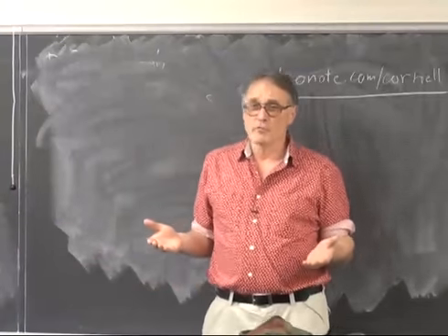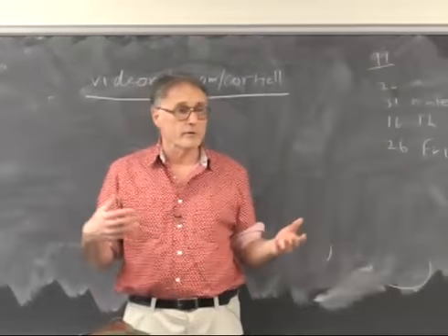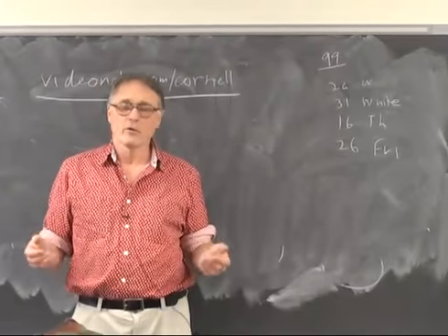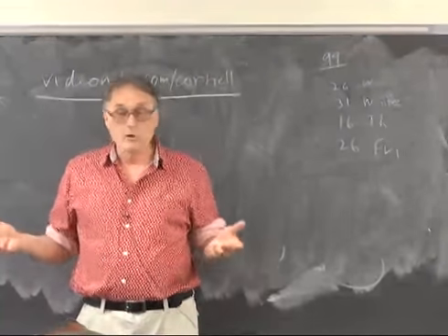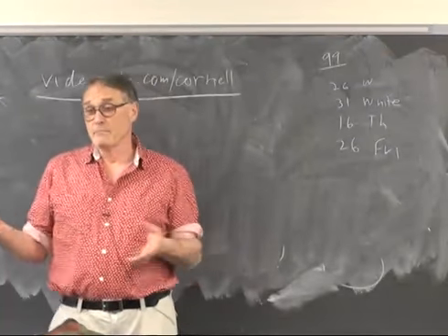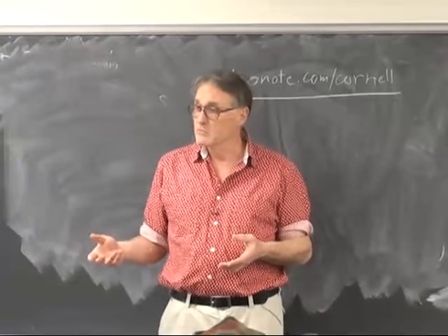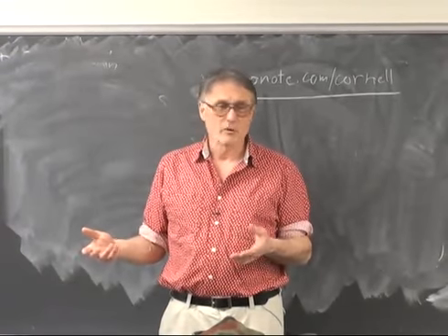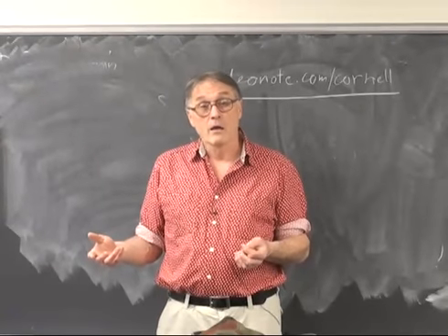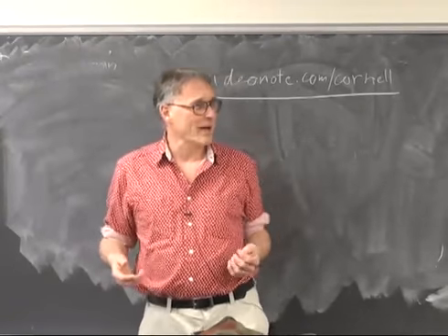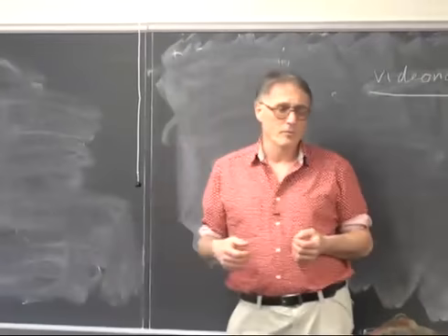And the dispersion for red LEDs is, anybody have a feeling for the turn-on voltage of a red LED? About 2 volts, plus or minus 0.1. Depends on the wavelength. Green, 2.5 volts. Blue, 2.6, 3. Ultraviolet, 2.9. Actually it's about 4 volts, 3.9, 4 volts.